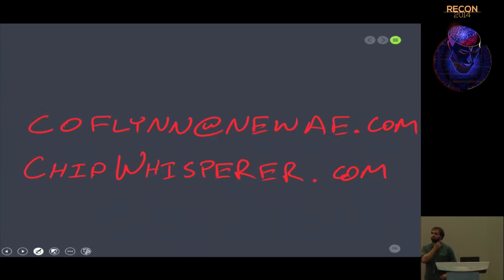To what, sorry? So the question is if it's tied to the size of the FPGA. The FPGA on this board, you mean? The limitation on this board is, yeah, it's a low-cost FPGA, so it can't run very fast, and the ADC itself has a speed limitation. Because it's designed to be fairly cheap, it's very limited in that way. You can buy fairly easily SDR type platforms that are more or less doing the same thing for a few thousand dollars, and use that instead.